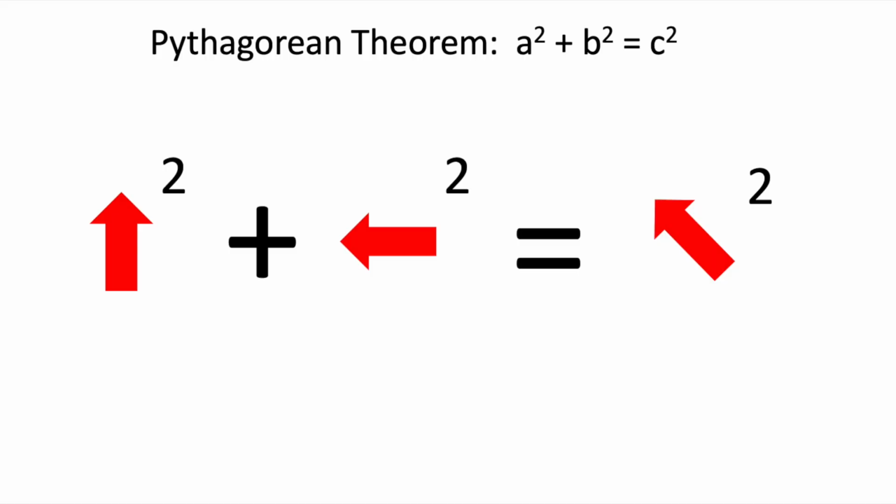And you can use a bit of trigonometry to find these, but what we're more interested in is using the components to find the overall tension in the cable, and that would be done by using Pythagorean theorem. So the square of each of the components summed together equals the square of the total tension in the cable, but we'll come back to that in a second.